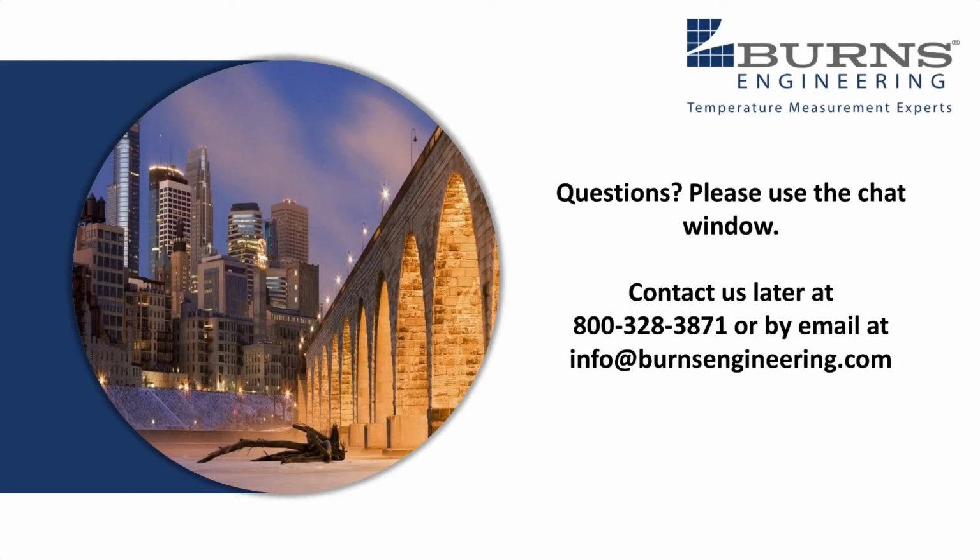So you can't look at that sensor and say, okay, it's got a time constant of 4 seconds, and I'm going to stick it in here and wait 4 seconds and I've got my temperature. That's not it at all. You're going to have to wait 16 seconds for it to really stabilize.